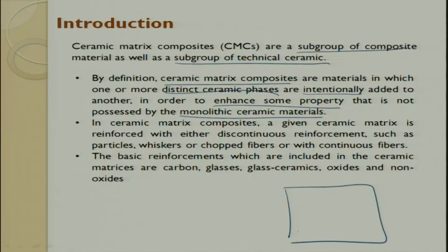What happens when you add particulates? When you have a ceramic and you add particulates in it, and a crack grows, the crack is getting diverted or distributed, or the crack energy is reduced and it goes around the particles, and when it goes around, the energy is dissipated, and because of this dissipation the crack does not go further. So, the toughness property increases.